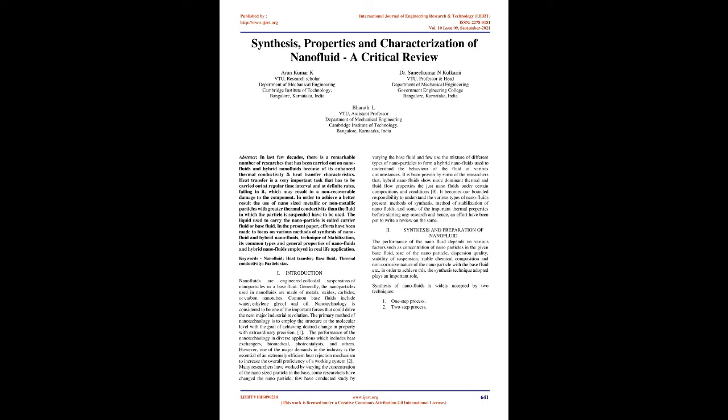One-step method. The process of preparation of nanoparticles is done by simultaneous creation and dispersion. Pulsed wire evaporation is the most promising method of single-step preparation technique, which consists of a high-voltage DC power supply, wire feeding system, capacitor bank, condensation chamber, etc. In this method, a high-voltage pulse is directed on a thin wire that melts and evaporates it within microseconds due to the effect of non-equilibrium heating.